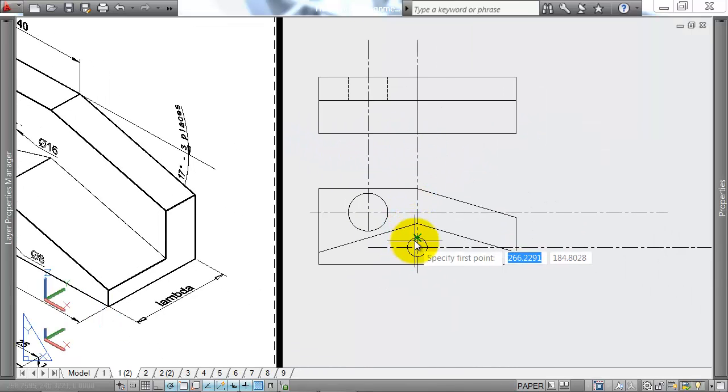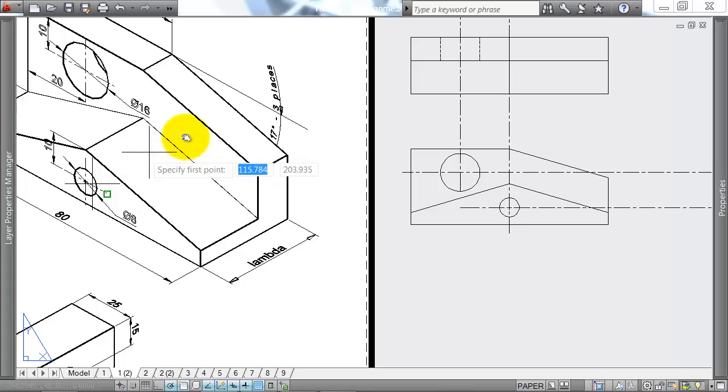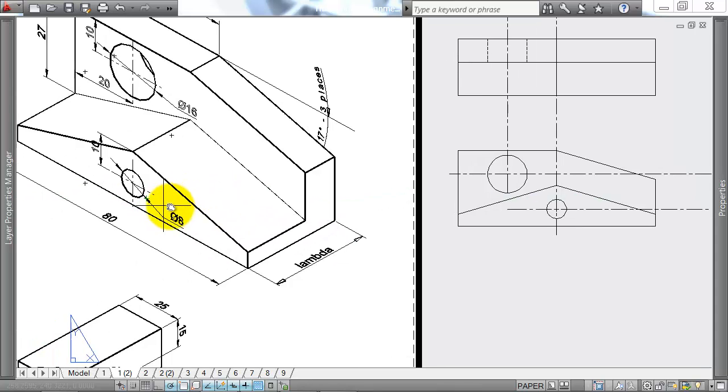And in this front circle, that goes the whole way through the shape. Now, if a circle is drilled through something and you can't tell how deep it is, unless the drawing specifies that the circle has a known depth, then you only put it into that known depth. But if the hole doesn't have a specified depth, you always assume it goes the whole way through the shape. So from this edge coming up, go through there, and this edge coming up, go through there. Make both of these hidden as well.